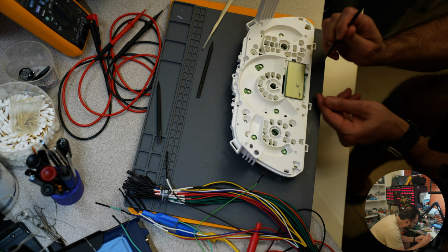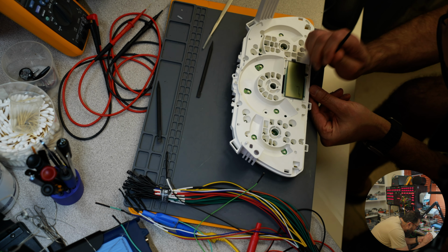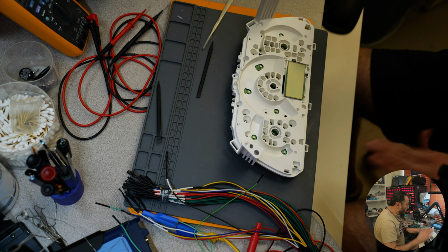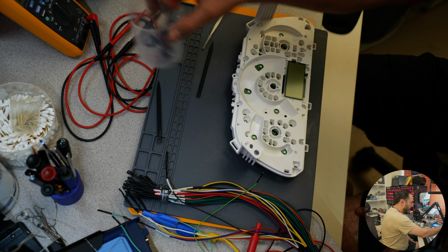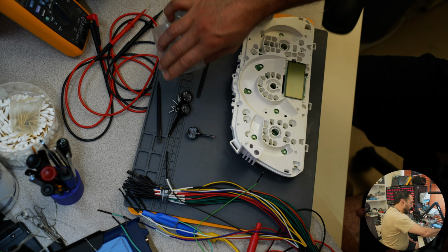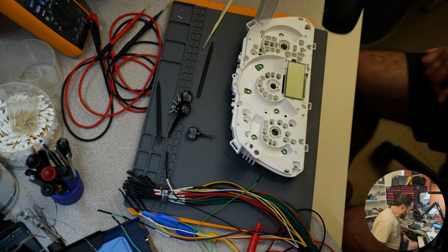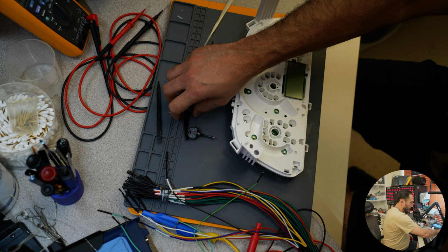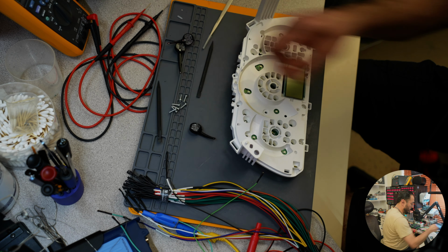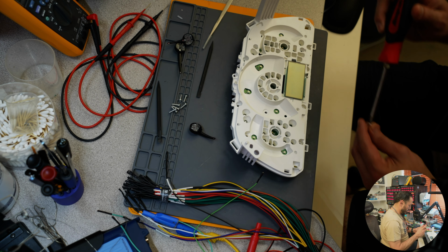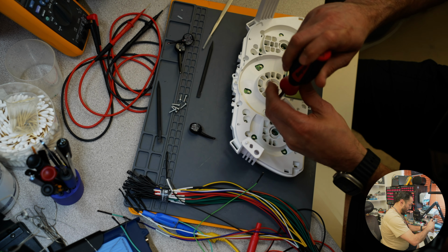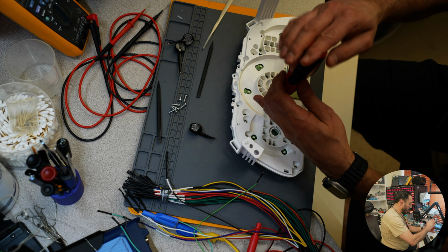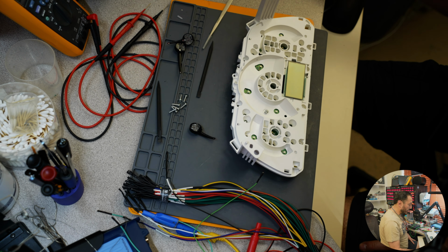I'm using a plastic tool just in case you're wondering what I am using. Very careful. You need to align that in there. Don't push it all the way in yet, because we want to make sure that we can set all the screws. These are Phillips head screws. And then 3 needles for the instrument cluster. I always set this one first in here, because this is the one that guides me in here. I don't tighten them up yet.